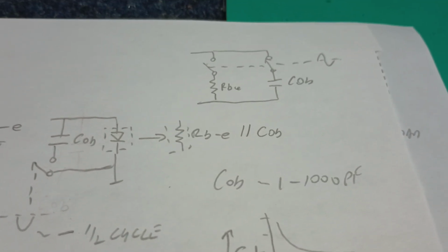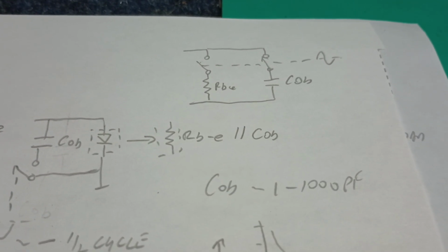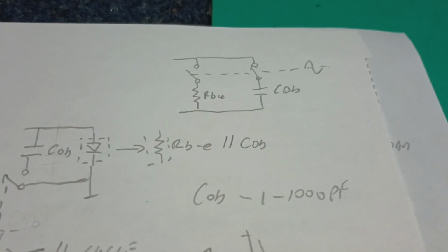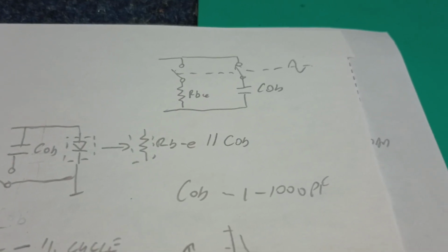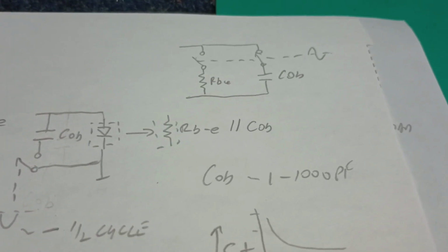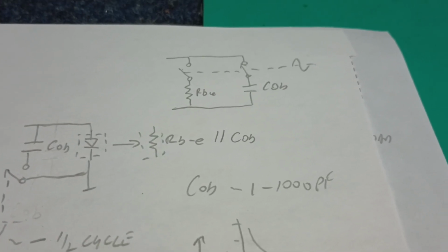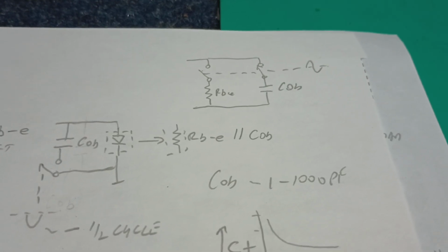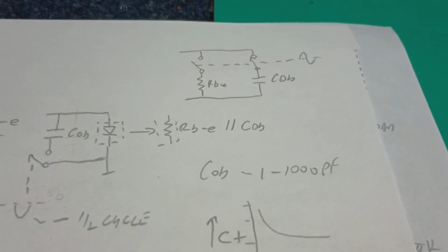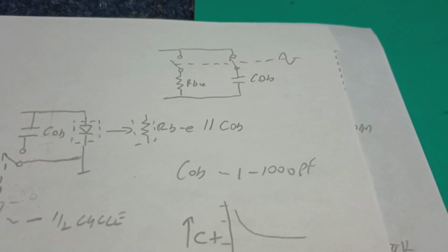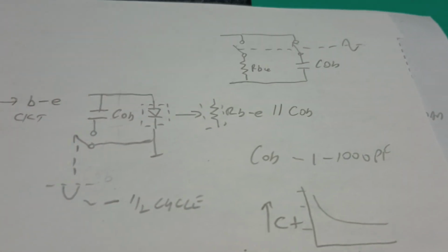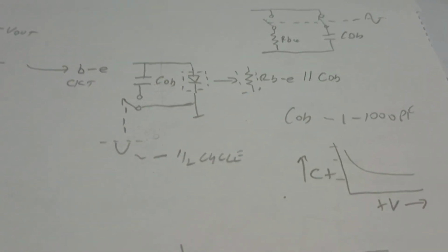that's voltage dependent. At 1 volt, the capacitor might be 300 picofarad, and at 5 volts, it might be 10. And we might like the 10 picofarad figure, but we can't get there without a significant reverse voltage on a transistor, and many transistors can't take much more than 5 or 6 volts reverse. They go boom because the voltage tries to pull the junction apart.